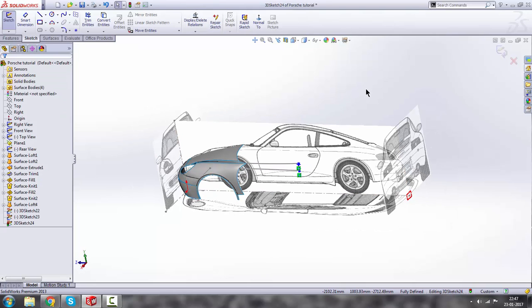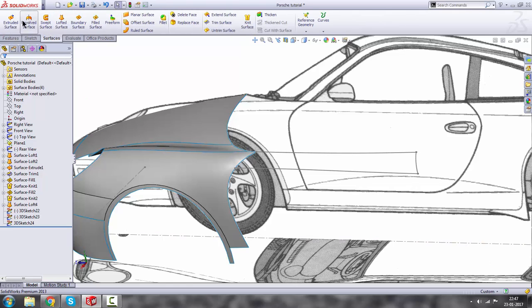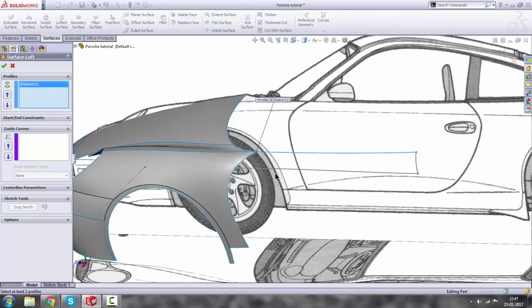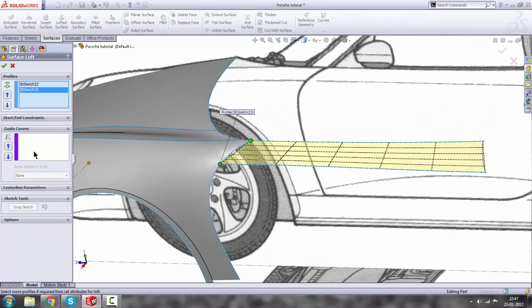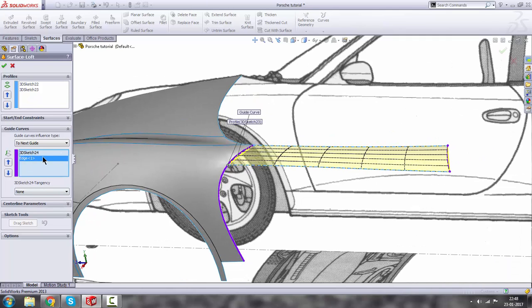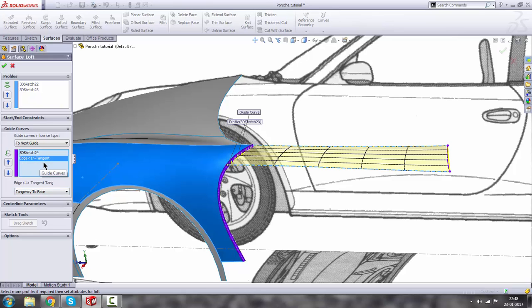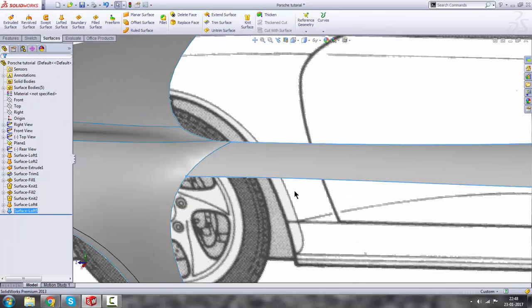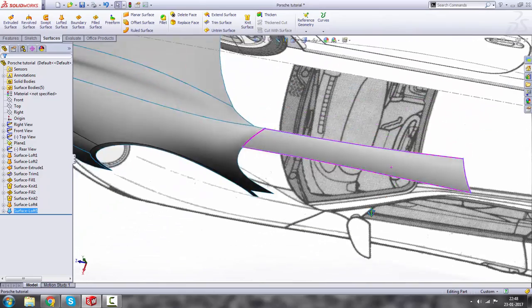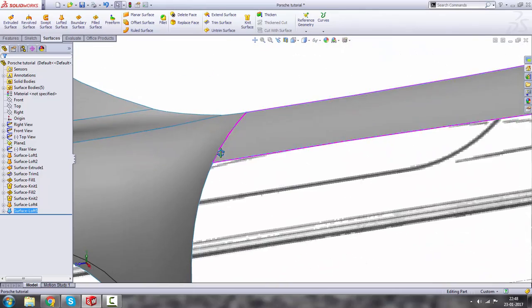the problem. First, you can see we have to see the surface, what kind of surface it forms. So go to surface, click on loft, select this sketch and click on the other sketch, and for the guide curve we are going to use this spline and this edge, and if we can provide a tangent relation with this edge, keep this edge selected and click on the tangency to space. It doesn't allow, okay, it does allow the tangency. Okay, click OK. You can see the tangent surface, and which is good, and not 100% tangent, but it will work.